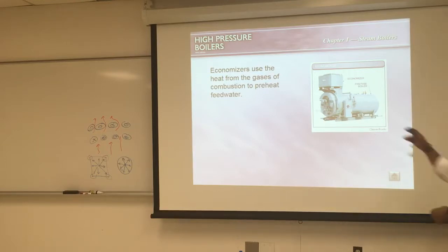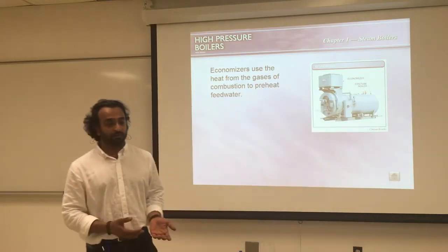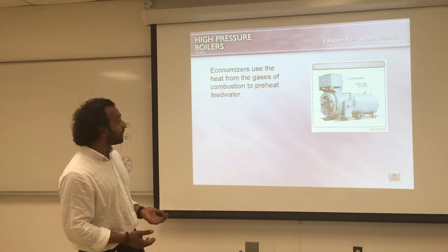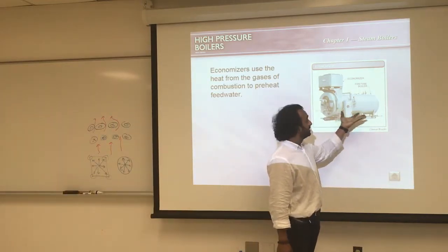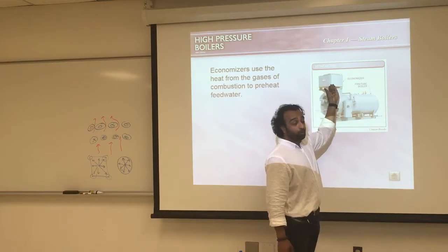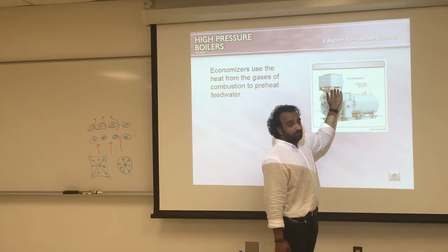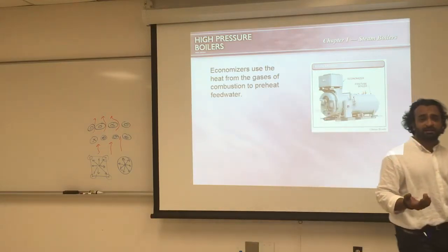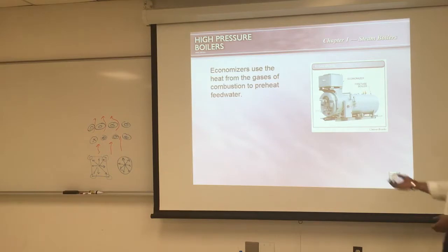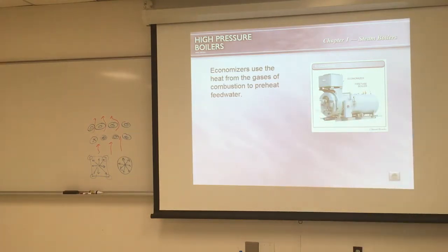Let's think about it. Remember what I told you earlier, that you don't want the temperature coming out of the outlet to be too low. So let's say we're firing too much gas inside the chamber, but the air coming out is too hot to be ejected to the atmosphere. And there's some useful heat that we want. So we can use that heat to heat the water coming into the boiler. So the water is not coming in at 40, it will come in at 150, so it's ready to be evaporated. That will save me some money by capturing all the heat that's leaving the boiler.